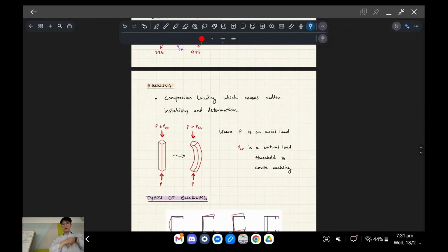Okay, because I know this is very late, I'll be covering buckling mostly online next week or whatever. But I'll introduce you to the general concept, because your week 3 quiz will definitely have tension and it'll definitely have compression. The idea of compression is unlike tension. With tension, I'm pulling this rod, and it gets more straight if I pull it. But if I push on it, it starts to do this. It starts to buckle. So why does it do this?